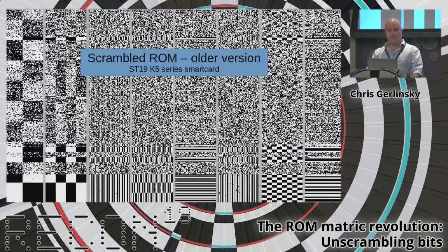So one of the pictures isn't showing up here, unfortunately, for technical issues. If we look at the decrypted version of this ROM, then all the areas with the really black and white checkerboard areas, those actually did decrypt perfectly to 0. Those were just empty spaces, and then we have code in the rest of the space. So being able to visually see these patterns is the whole basis of how I'm descrambling these ROMs.